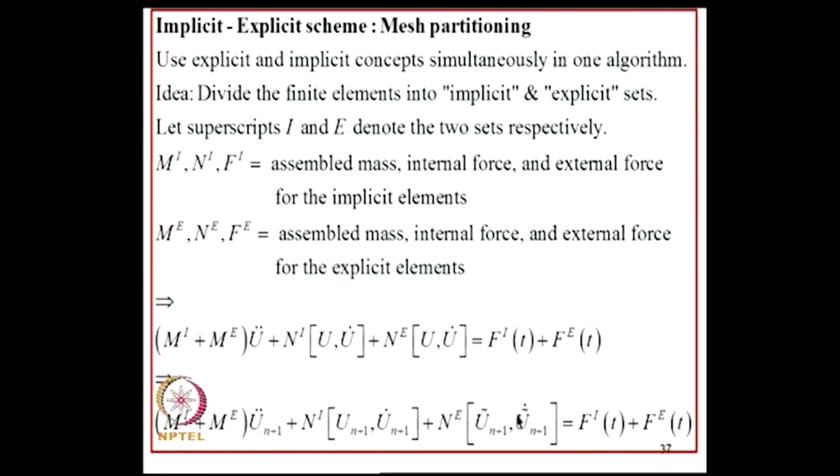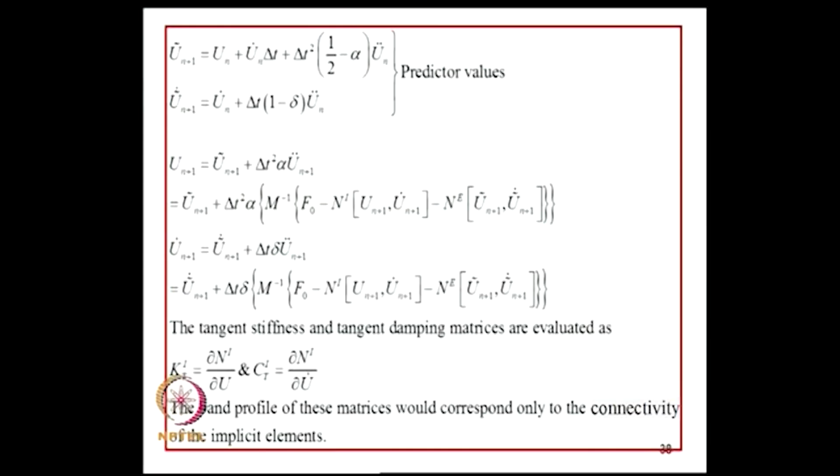Okay. So, the idea is when you solve the nonlinear equations, you will be using Ni, not N. And this will be the structure of the matrices that you encounter, and their bandedness features etc. are controlled by Ni, not by N, and Ne makes no contribution to that in your solution of the nonlinear equations. So, the effort in solving the nonlinear equations can come down substantially.